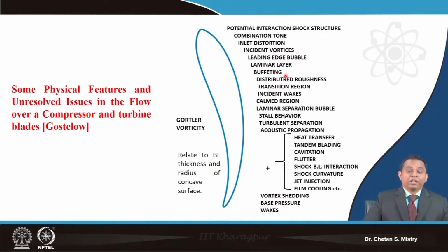And you can understand we are looking for our suction surface to be a perfect surface. Other than this, if I have sticking of air, say particle or dust particle, on this surface, that will change my flow physics on the suction surface, and that is what will give off-design performance. It means the compressor will not work according to our expectation, and that is the reason people do compressor washing after a few flying hours.